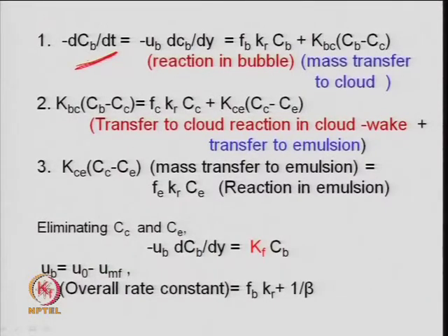So, you can very easily write down the rate of disappearance of B, which you write as minus dCB by dt, that is the change in concentration of B with respect to time, the rate, right. And you know now that FA0 dXA is equal to minus rA, and that is here mentioned in terms of the convective term, which is FA at y, which is written in terms of CA into U times A, right.